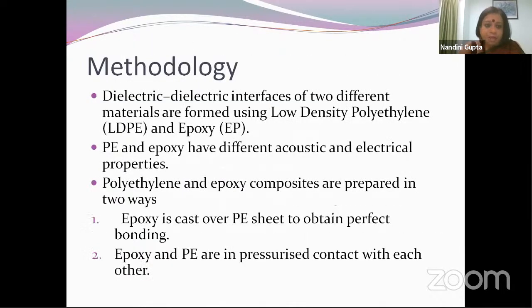So in this case, what we have done is we have tried to see how this interfacial polarization can be measured and how this interfacial polarization modifies the electric field within the material and changes the space charge accumulation within the two layers. So we have taken dielectric interfaces of two different kinds. I'll explain as I go along. We have low density polyethylene (LDPE) and we have epoxy.